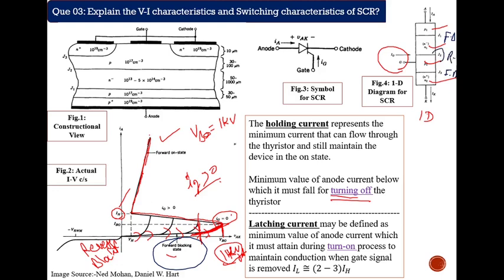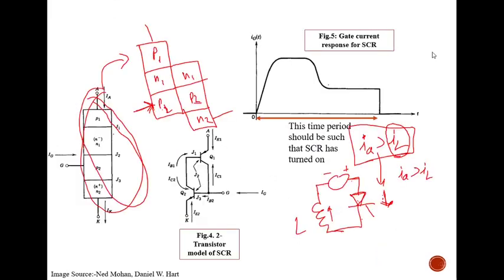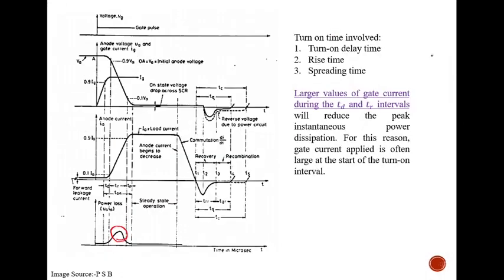If you come into the forward on-state mode, because forward on-state mode and forward blocking mode are stable modes, then J2 comes into forward bias, and current can flow easily. If it is reverse biased, then current will not flow. In the reverse blocking mode, the junctions are reverse biased, or maybe one of the junctions may be forward biased.